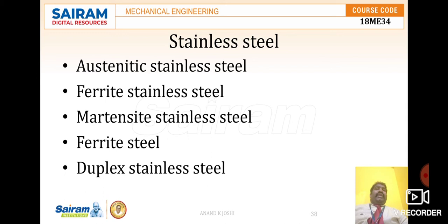And next, ferritic stainless steel means around 12-22% chromium with very little nickel and carbon content, along with molybdenum, aluminum and titanium, which are mostly added to obtain favorable properties of such kinds of steels. Okay, and ferritic stainless steels are used in computer floppy disk hubs, automotive exhausts, hot water tanks, etc.